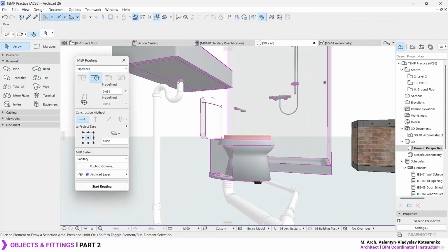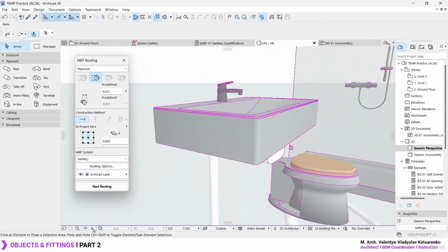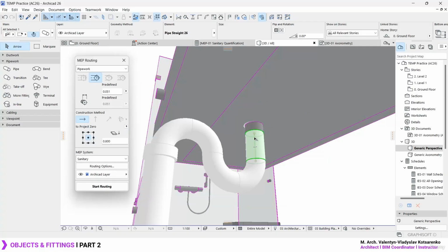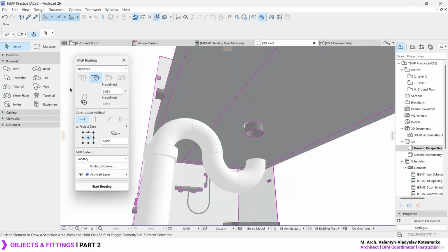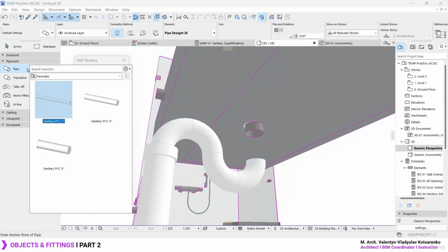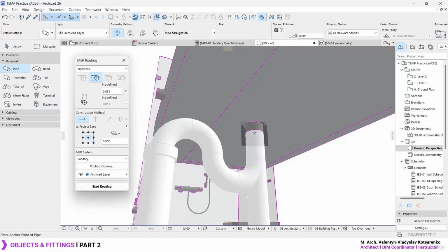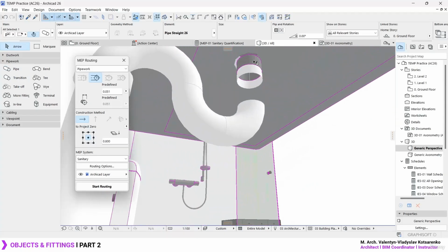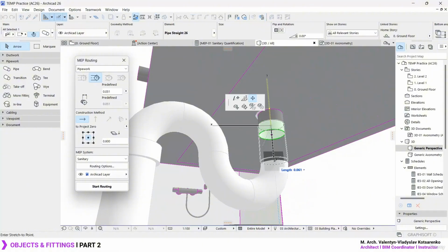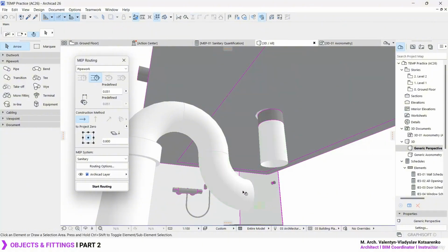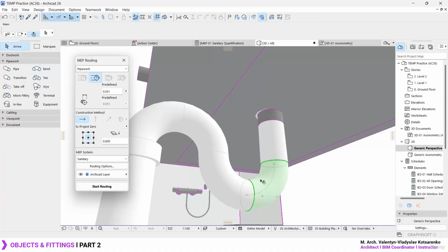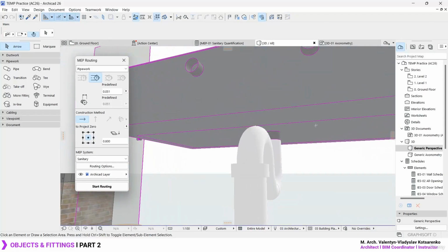And there we go. Well, in my case, I simply decided to model everything in 3D. Just for this part, if you notice, I simply clicked over here. I'll repeat the process. We can, for example, select the 2-inch pipe. Just left click over here and it's going to automatically set the direction for your pipe. So you can simply start off over here, left click, and then you can simply go ahead and left click over here, set your first bend, then set the next one, which is this one, set the next one and the next one. And simulate any type of special connection you require over here.